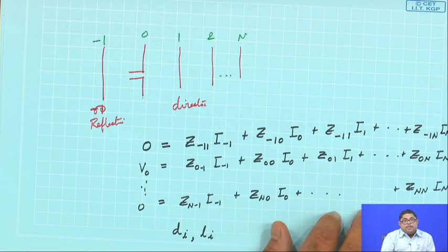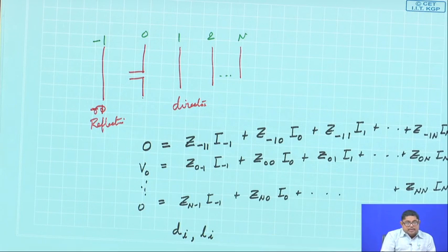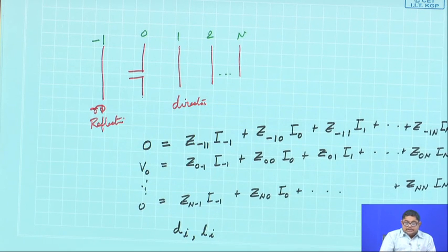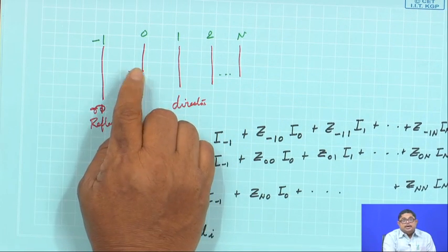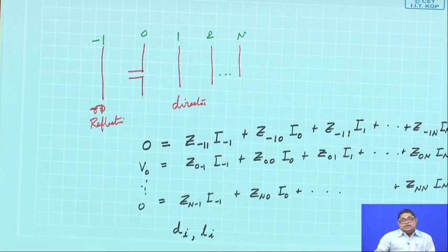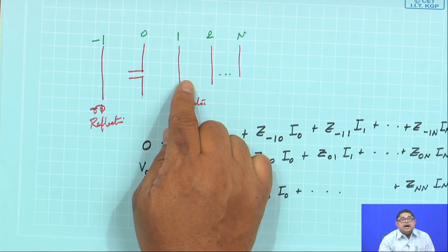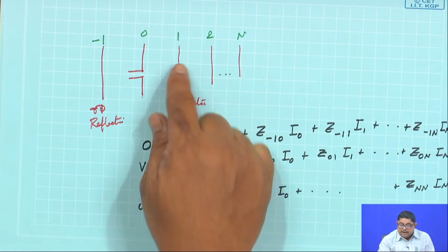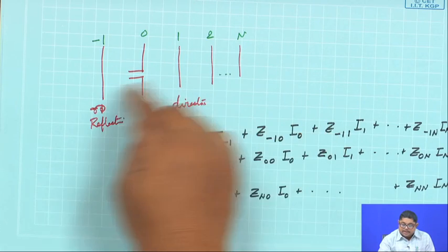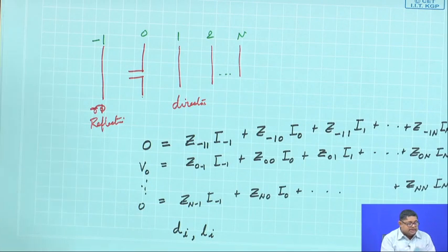Now, the serious problem of this parasitic array is that the radiation resistance at the terminals of the driven dipole becomes quite low. It is not the 73 ohm that we get for a dipole. That is because some of this energy is not radiated; it gets obstructed by these directors and reflectors, etc.